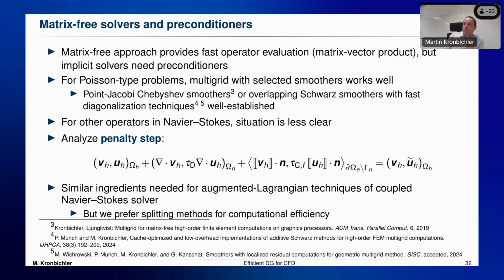I mean, we can do Raviart-Thomas in deal.II, but I wanted to focus on this one because you can do it very efficiently. Now I just picked out these terms that we do in the penalty step as a weak form. Essentially what we need to do is integrate over this u tilde, an intermediate velocity, and then we want to get the end of step velocity u_h, which is subject to these additional constraints.